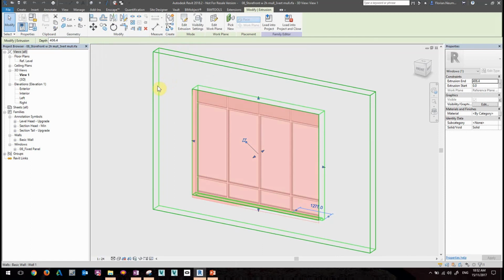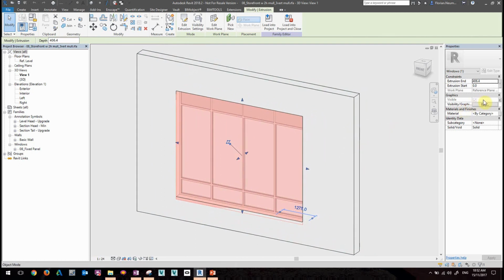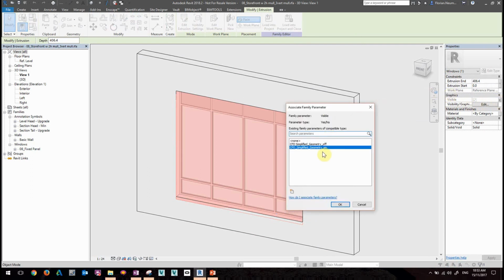So with every geometry I model, I can make use of the instance parameter I have within my family. Same game: contextual tab, options bar, properties, type properties, symbols, and one of the instance parameters is my visibility. And the visibility parameter I can connect and hook up with a family parameter that I can turn on, turn off.